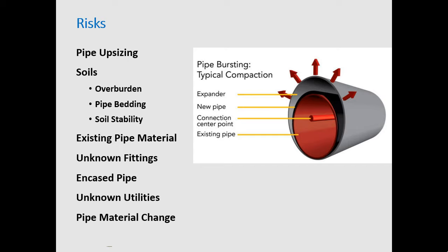I think the answer is what the city of Anchorage is generally obtaining is adequate. You want to know if you have sands, clays, where your water table is, your densities, your spoon tests. That type of information is going to be adequate for most geotechs to help with these recommendations. You want to know what the density of your soil is and what you're trying to burst through.